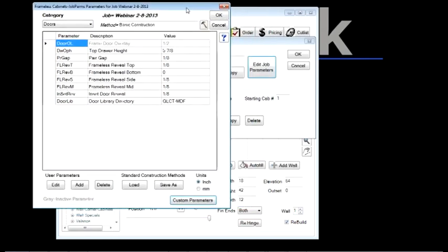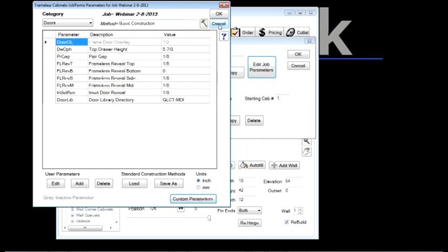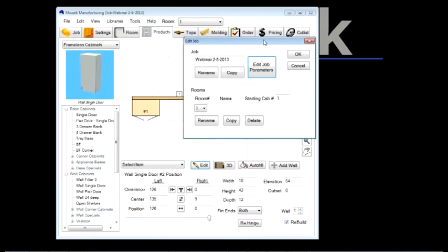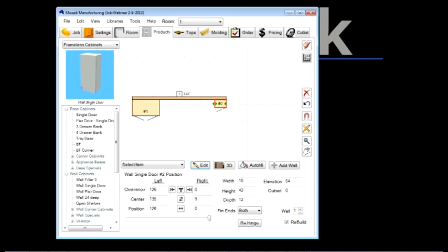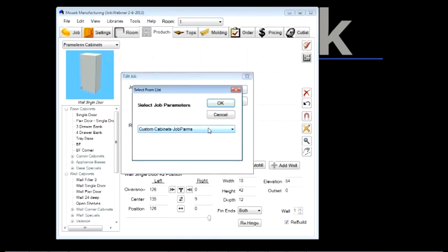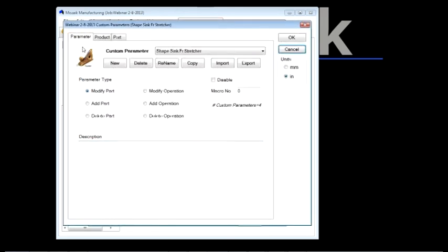And then here's one other quick question while I've got you here. If you were adjusting the nailers down, if there's an operation associated with the nailer to the end gable, would they move too? It would not, because remember, when you're at the parameters and you go to modify something, if I click that, I'm modifying those partitions.